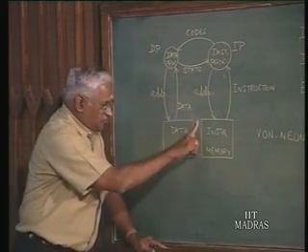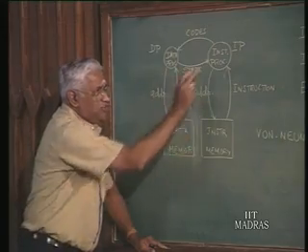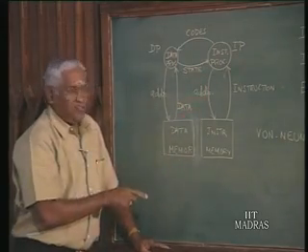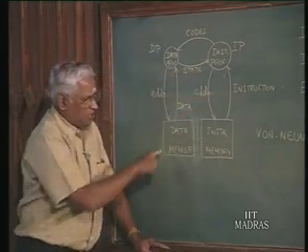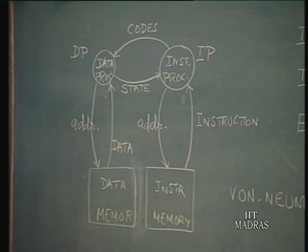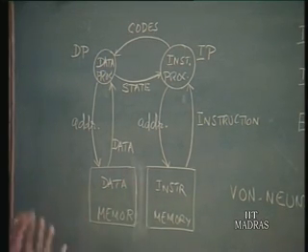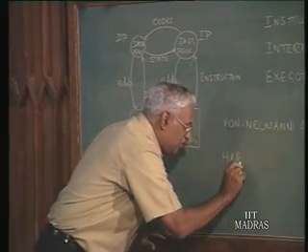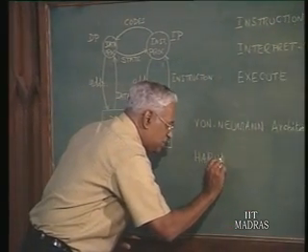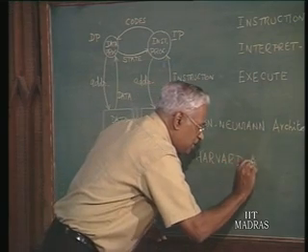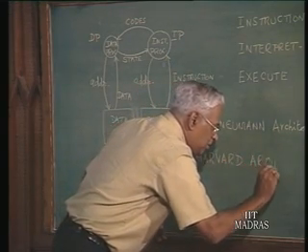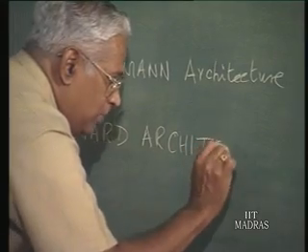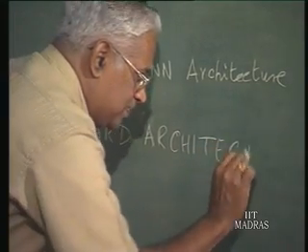This first step, that is having two different means of accessing the respective part of the program, that is instruction and data, which really gives rise to a data bus separately and an instruction bus separately, not having a single common bus, had in fact given rise to what is known as the Harvard architecture, in which you have these two buses separately.